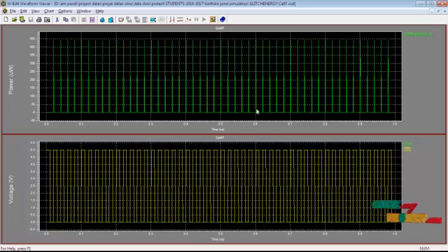The overall glitches are reduced in the output waveform voltage, it also improves the conversion rate, time is reduced, and overall area is reduced. So using binary weighted current steering digital to analog conversion has a lot of advantages over conventional digital to analog conversion.